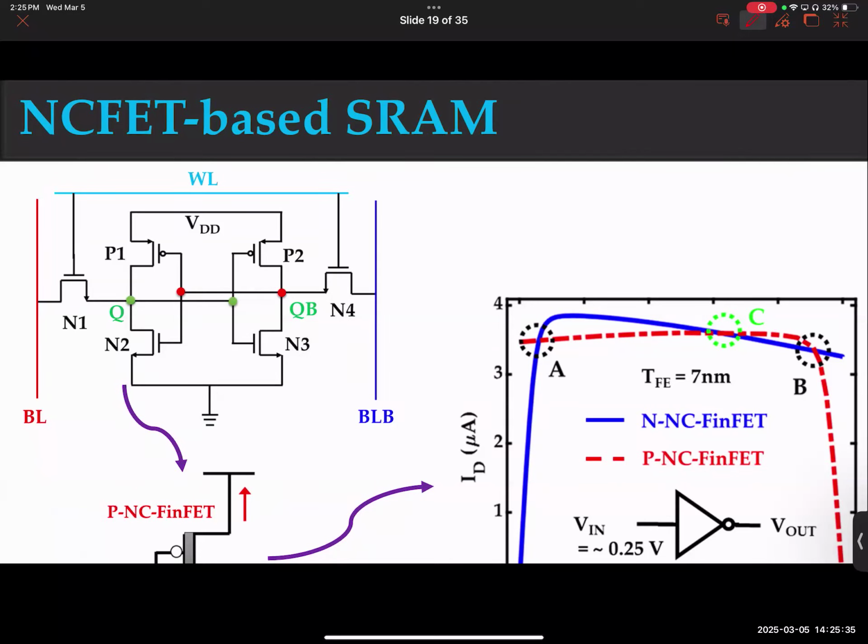It will drain, yes. The reason why SRAM has no respite from this problem is because, to hold on to the data, you need what? I'm pointing to it. You need VDD. If you remove VDD, these cross-coupled inverters will no longer work, and you lose everything. You lose everything. There is no data left. So you have to keep applying VDD.